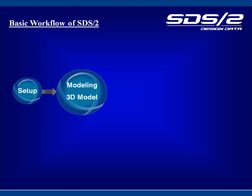Next comes the building of the model. A few basic points about the model are: SDS2 uses the term members instead of what some software would call assemblies. Bolts and connection material are part of the members as well as any user-added material. For example, when a material is added for a member, like a pour stop, no additional operations are required to connect the material to the member.